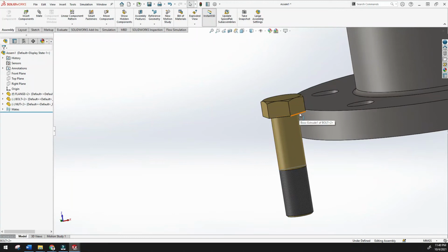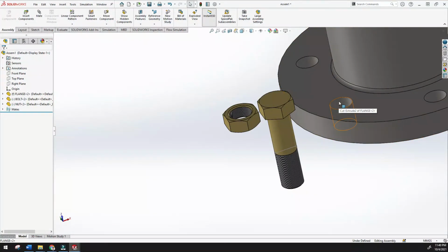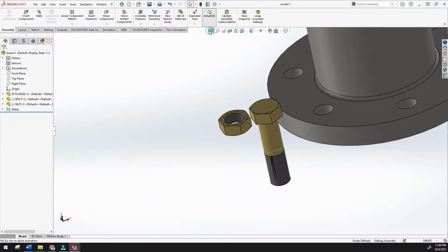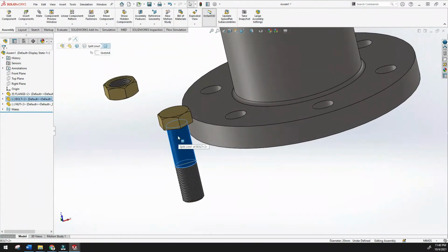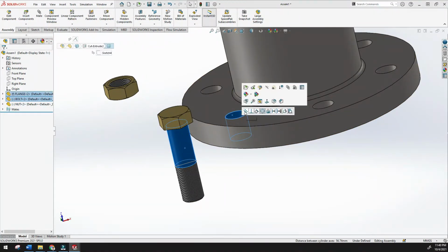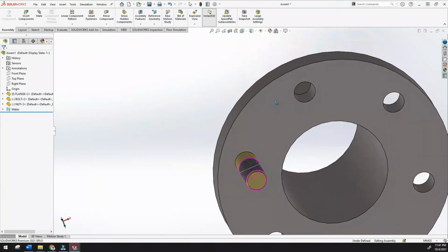Now it should be here on this hole. Okay, so how to give it? Just click this cylindrical part, and Control-click this part. Here again it will come out, and you can see so many options automatically appear. Here you will see concentric, you have to give the concentric mate here. Okay, it must be suitable, and here you can see it is automatically fixed with the holes.